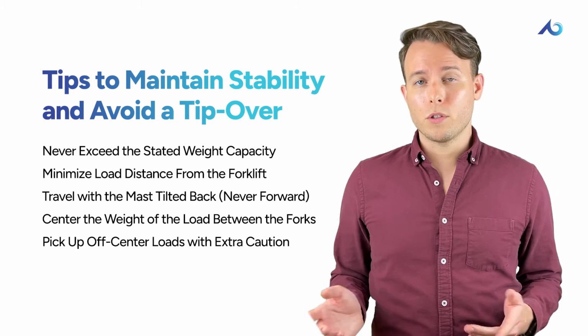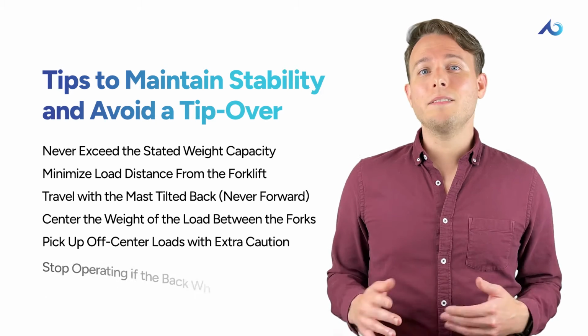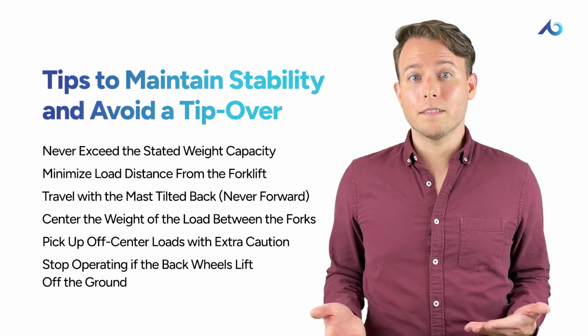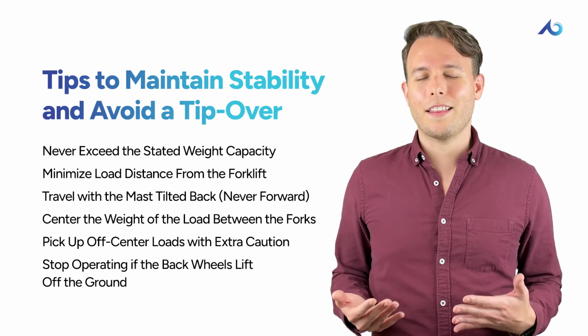Pick up off-centered loads with extra caution. And stop operating a forklift if the back wheels begin to lift off the ground, since this is an indication that the forklift is overloaded.